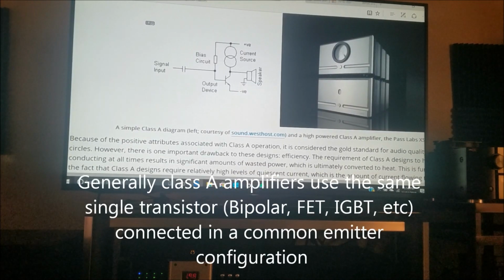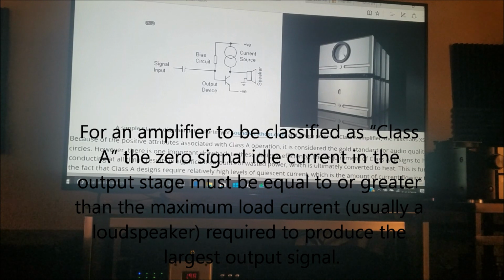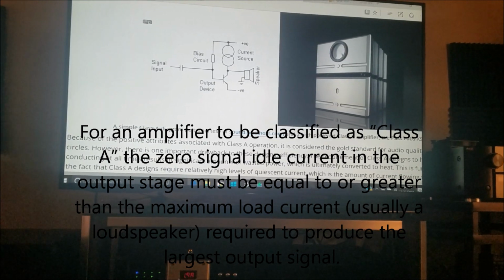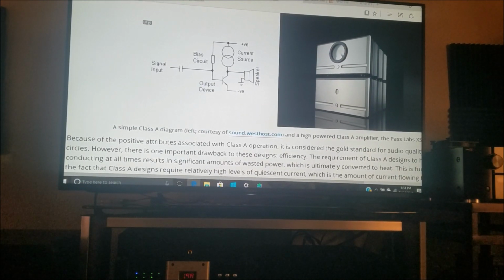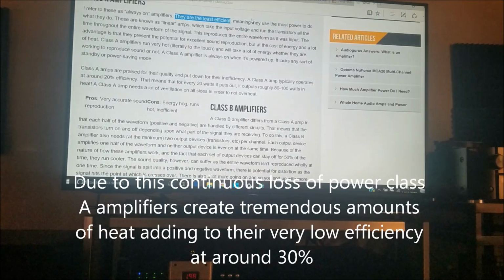With Class A amps, because there's never an off time and they're always turned on, there are no problems with charging or storage, or time to turn on, time to turn off, and for another playing device to take the task of the first one. Which generally means a higher frequency performance with better stability and less higher order harmonics. But Class A power amps are generally meant for lower power needs.